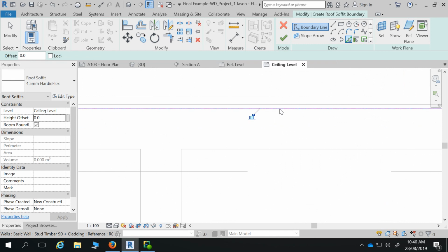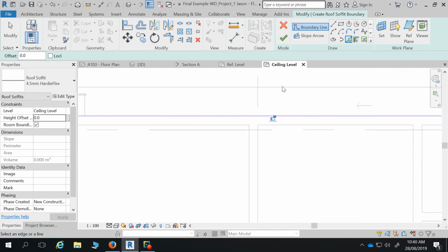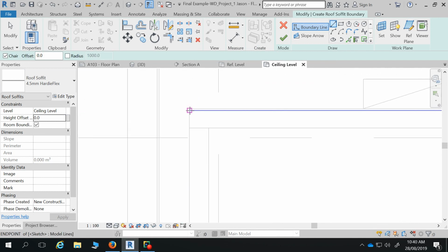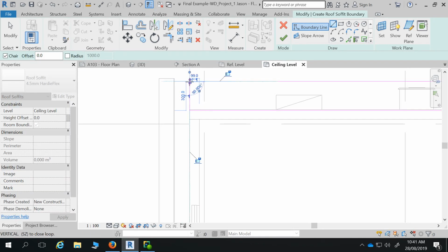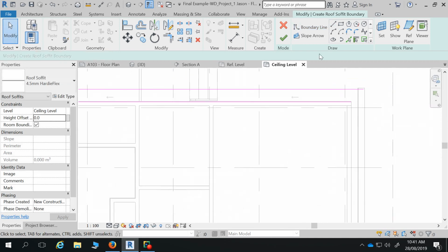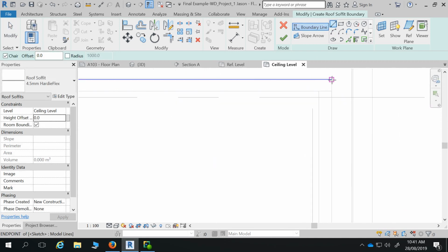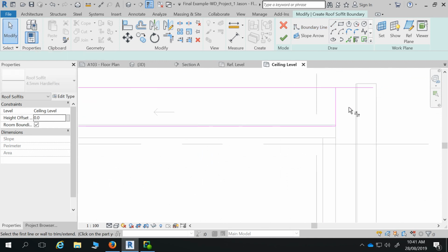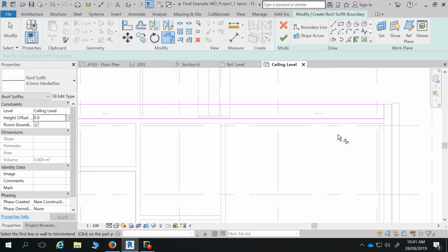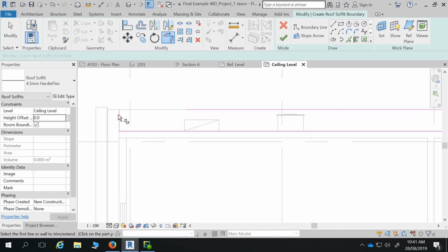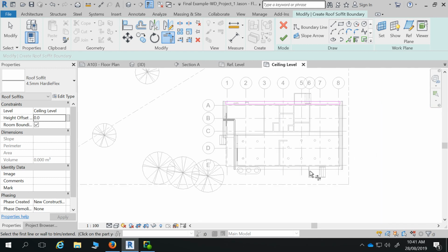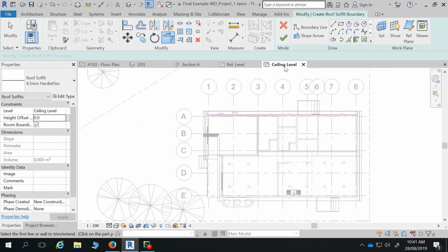So that's the stud there, and then I'll pick this roof to start with, and then I'm just going to sketch 2 lines to straighten up the ends. So that's where it will finish, and another one here. So just at the end of the house, don't extend it to the overhang on the gables. And so you could, in the same sketch, do this side as well. And once you've done that, you just tick it.